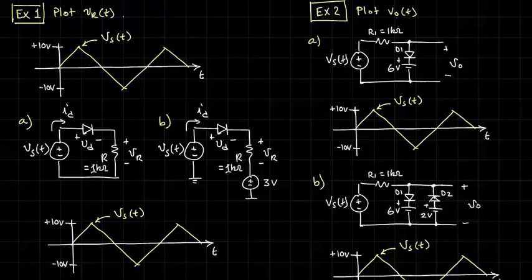We're not told specifically any characteristics of the diode. So typically, if you're not given any characteristics of the diode, you would have to make an assumption that the diode will be modeled as a 0 volt ideal diode. Okay, so it's either 0 volts when it's on or it's an open circuit when it's off. That's what I would do.